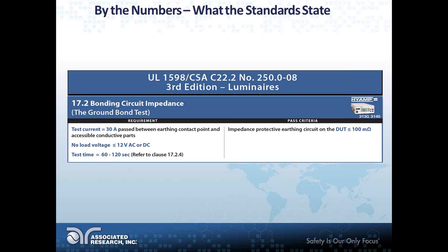So they want you to be able to stress that for a long enough period of time to prove that your ground circuit's going to be able to handle that fault current for the necessary period of time. In the medical device standard, I don't believe they actually give a time. I think they just say a time necessary enough to obtain a meaningful reading, which, you know, maybe you don't need a full 120 seconds, but with the ground bond test, since you're dealing most of the time with an AC current and you're loading down the circuit with high amperage, I usually run it for at least 5 to 10 seconds just to make sure that it can handle it for a specific period of time.